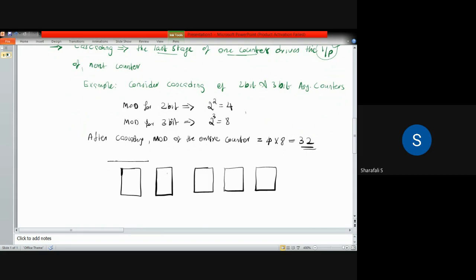This will be connected to logic 1, and that is connected to this K0, and we apply the clock pulse here. This is your Q0, and that is given to the second flip flop as its clock, and this is connected to the common logic 1. Here we have J1, K1, Q1, all those things.